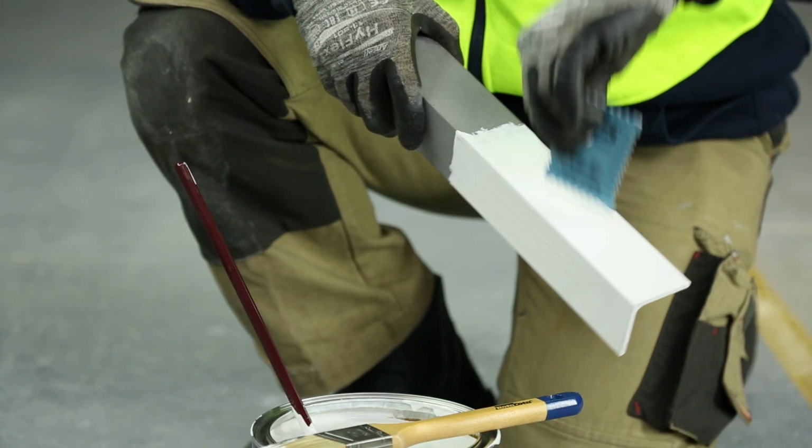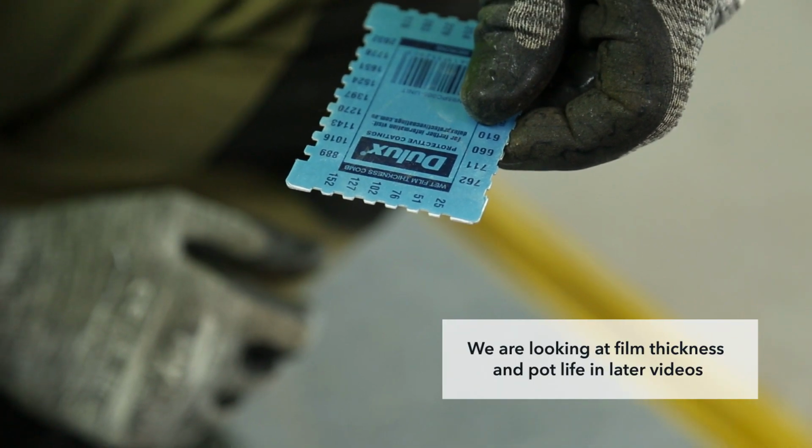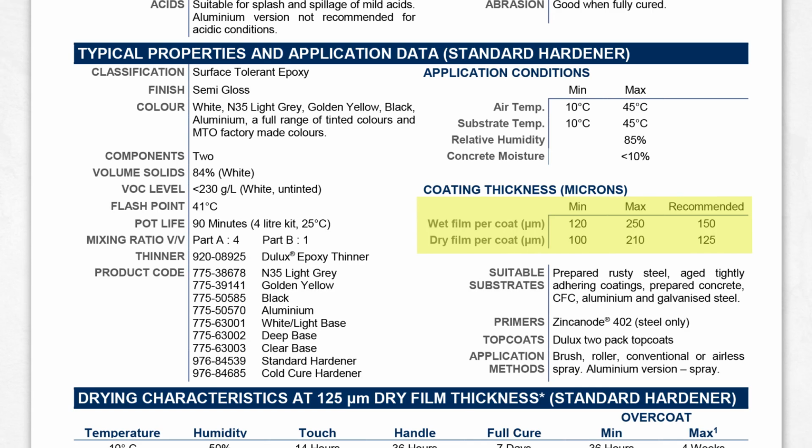It is essential that a wet film thickness gauge is used to monitor coating thicknesses during application. This provides peace of mind and ensures that the dry film thickness is achieved during the coating process. It also includes suitable substrates, primers and top coats, and application methods associated with the product.